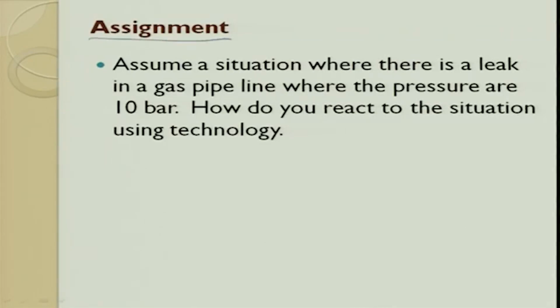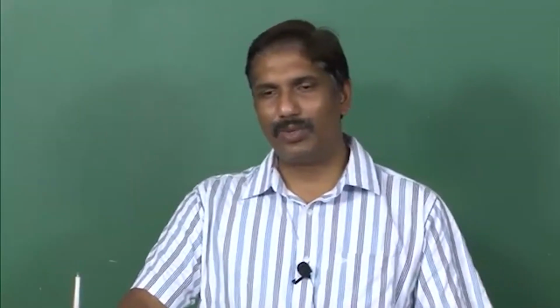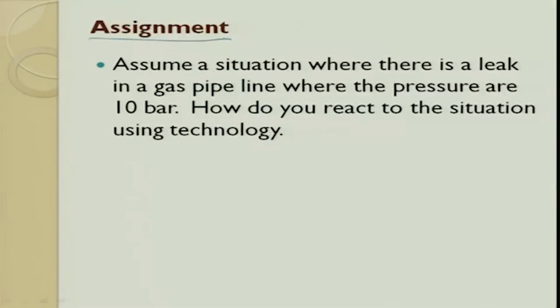With this we come to an end for this lecture, lecture number 9. In this lecture, we saw a process called the filament winding process, which is used for making cylindrical components, and we said that if there is reverse geometry, it is very difficult to use. In this process, you can have fibers at varying angles, you can do varying windings like helical winding and polar winding, and you can give strength depending on requirements. You can keep playing with the winding pattern and the richness of the reinforcement; all these things play an important role in getting the required output.